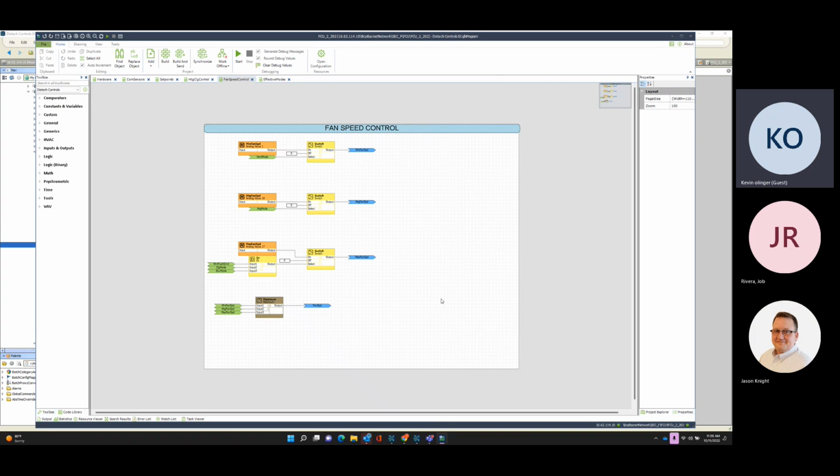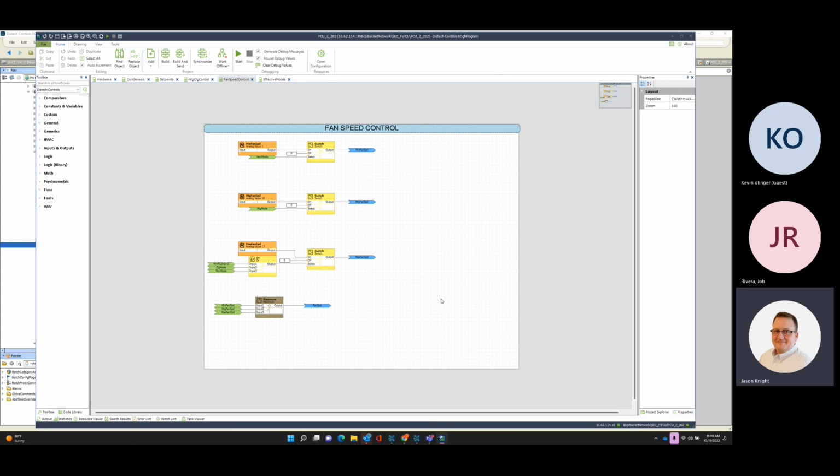And that was going to be one of my questions. I'm assuming you're not getting feedback through the ECM motor or the package equipment. You're getting feedback through a CS, I'm assuming, correct? Yes. So we had to go with special current switches that read ECM motors. And those are better than a normal current switch, you know, go, no go, or adjustable VFD current switch. But there's challenges with those as well when you're running these super low motor speeds.